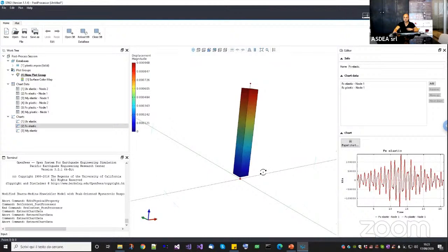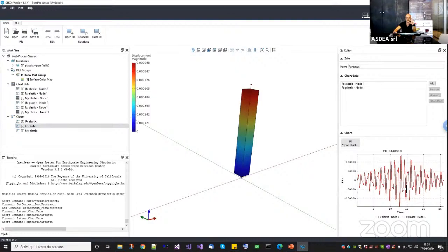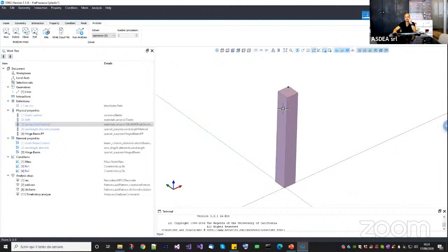So basically, what is happening? The problem is that, having a look at this, you already understand your solution is not in equilibrium, okay? But your solution has been accepted by the convergence test. So you can soon arrive at the conclusion that your convergence test was not small enough. Okay, so it accepted a solution which is not actually in equilibrium. That's why you have this problem. So to solve this one, you have a couple of choices.